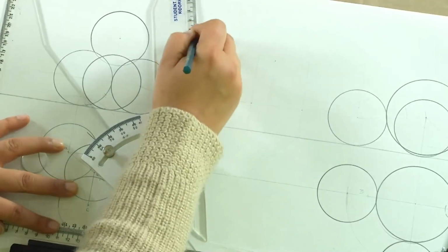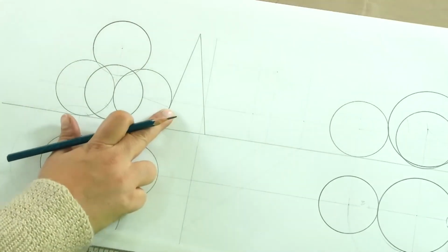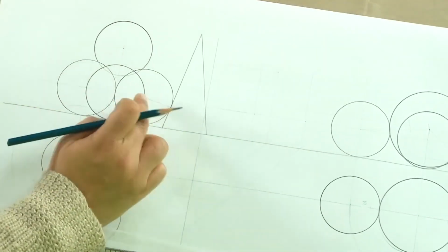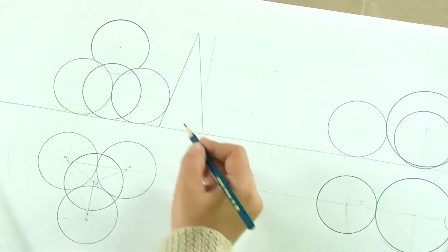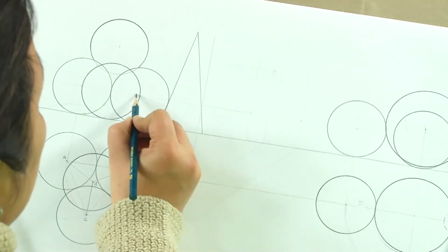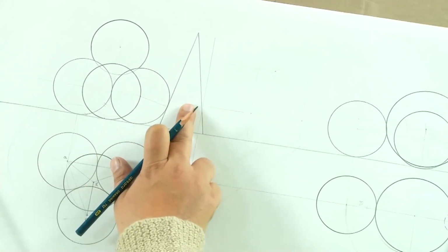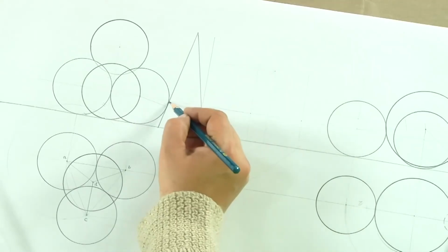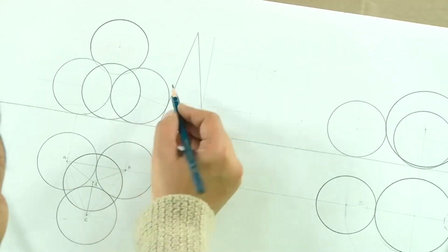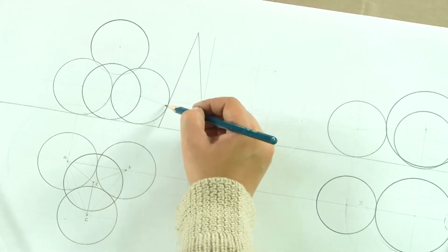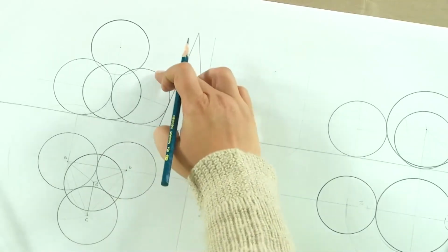a very sharp angled cone, and for this we had to make a sphere. So, what we would do in that case is we will actually be taking a line at the same height as that of radius in the cone, and then we will actually be drawing a circle at this given distance from this. So, we will be making a perpendicular from this and take a sphere which is just touching.